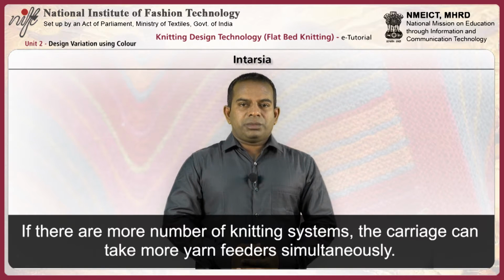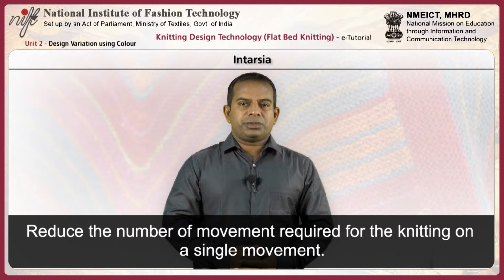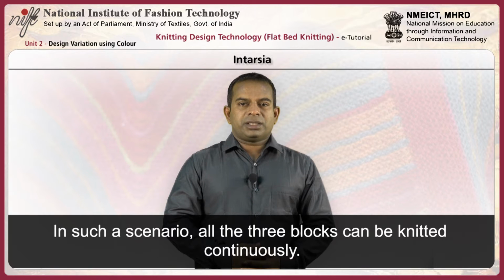If there are more knitting systems, the carriage can take more yarn feeders simultaneously and reduce the number of movements required for the knitting on a single movement. Alternatively, if there are feeders available with a kickback system, it will allow the feeders to kick sideways and go up, clearing the knitting needle to perform without any worry of clashing with the feeder. In such a scenario, all the 3 blocks can be knitted simultaneously.